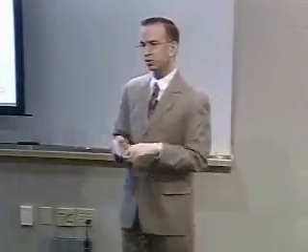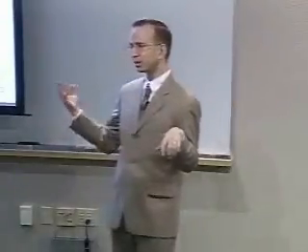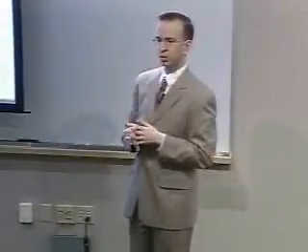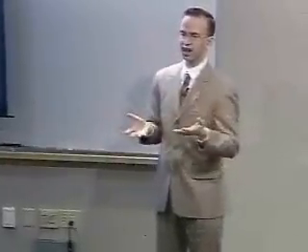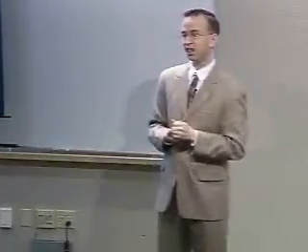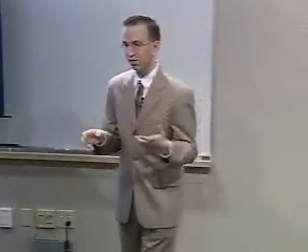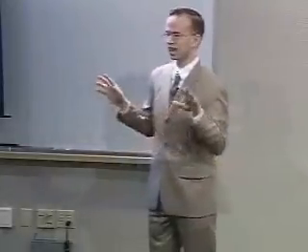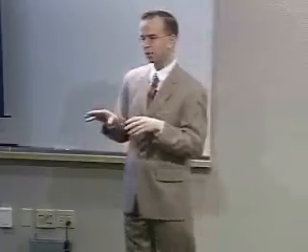I've also done some work on what we call chaotic networks. That is, everybody's going into the store, going into Fry's, buying an access point, plopping it in their home. How much interference is potentially there between these devices? And the quick result was that it looks like in metro areas there could be a lot of interference. We haven't laid on top of this an analysis of capture, which might say, oh, there's interference, but capture eliminates it.